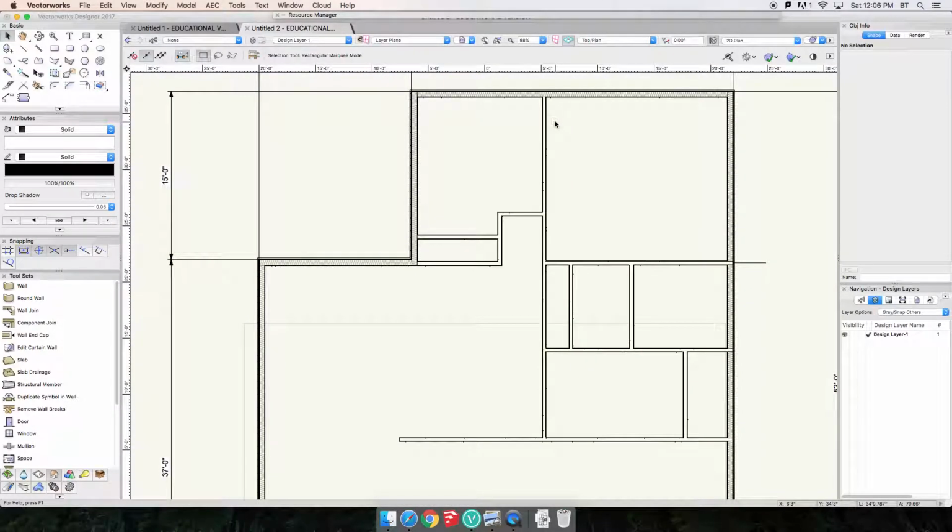Okay, so we've gone over interior partitions, so changing the drywall to 1/2 inch. For that first wall placement, we're going to use our line tool to snap off our exterior sheathing. Then we're going to use our duplicate move command tools so that we can place all our walls. And then we're going to go into our wall join and either T or L join all our walls that we've placed. And that was just a matter of a couple clicks.